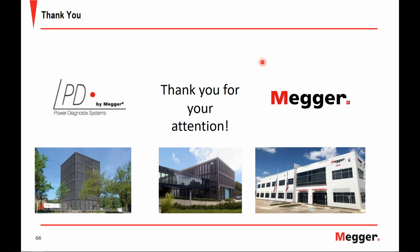If you have a critical problem within your insulation and the rest of the insulation is perfectly fine, your tan delta measurement may come back acceptable, maybe even good, whereas your partial discharge measurement will give you insight into that defect and let you know that it is in a severe location and needs some attention. With tan delta, you may only know when it's a little too late. So I wouldn't say there's a benefit of one over the other. I think they complement each other.